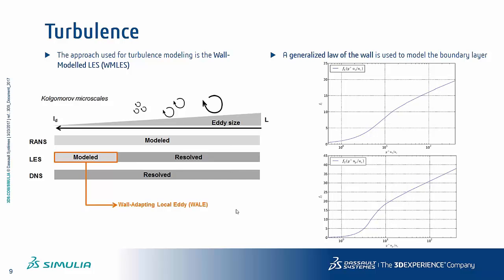So I was saying that LES is very expensive for the Navier-Stokes codes, and I'll demonstrate in this presentation with the LAGOON test case that it's true for an LES unsteady simulation. Navier-Stokes can be much longer and slower than a Lattice-Boltzmann code, and that's what I explain later.